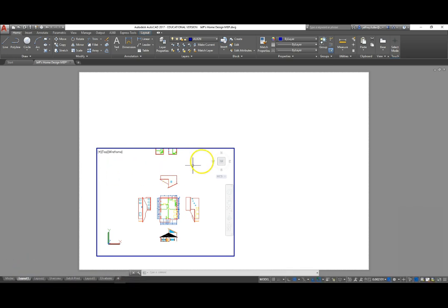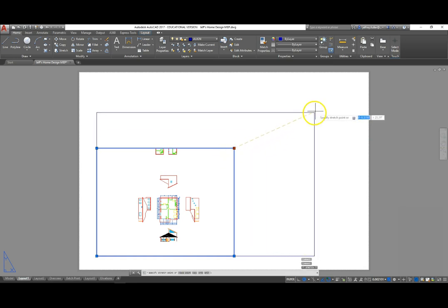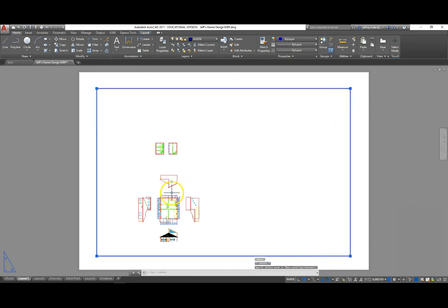You may notice that the size of your sheet has changed, but not your viewport, which is probably a smaller square in the bottom left-hand corner of this new sheet. To change the viewport size, click in the empty white space of the sheet to turn off the viewport, which is highlighted in blue. Hover over the viewport border with the cursor and click to activate these handles at each corner of the viewport. Grab the top right handle, click, release, and drag until the viewport is within an inch of the paper's edge. Then click to place.